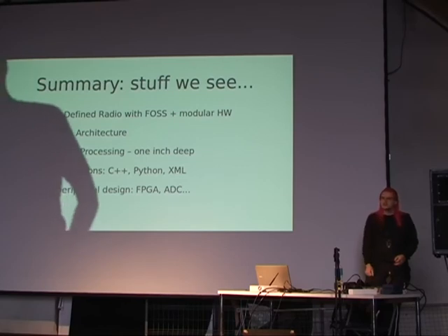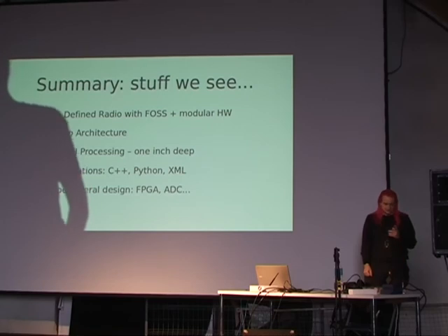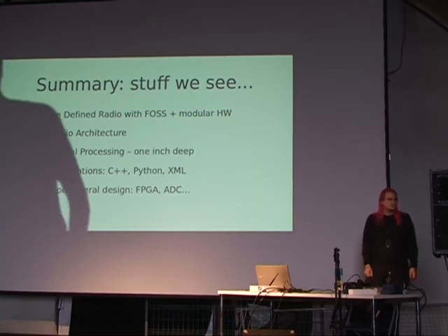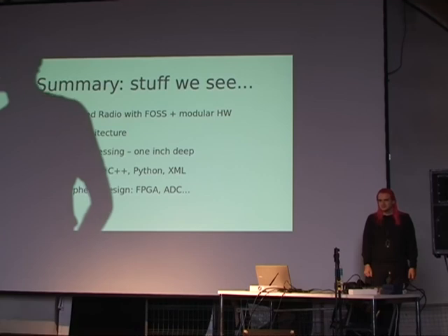GNU Radio is mostly used for rapid prototyping, so you don't necessarily optimize the power scheme of a real radio. Performance-wise, it is I/O hungry rather than using much RAM or CPU power. If you want to make a mobile device, you cannot use many watts, so in that case you could fall back to traditional approaches, since GNU Radio is just to prototype transmission and transceiver schematics.